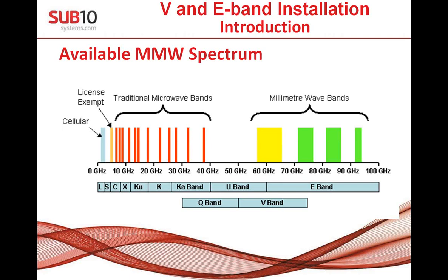And the second one is E-band, as Echo, and this system is currently used in two windows. You can see something between 70 and 80 gigahertz, and something between 80 and 90. Physically, it's from 71 to 76, and from 81 to 86. There is 10 gigahertz fixed duplex spacing between the lower and upper frequency band.